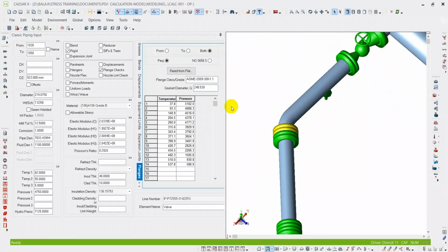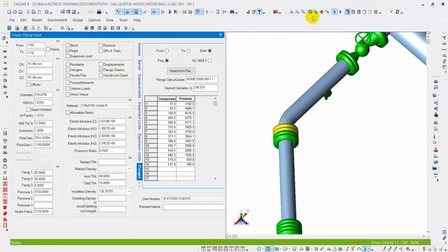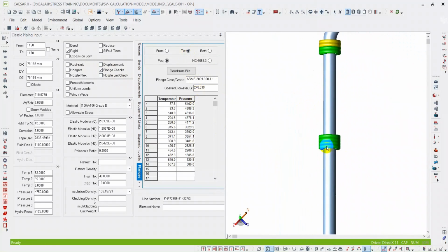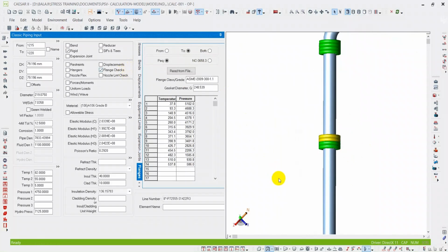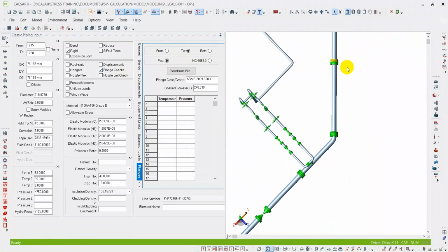Then go to this node and select flange leakage. So here we need to check the flange leakage at the center. So you have to define 2 because our modeling is like this. So we have the model like this from here and it is continuing. Okay. So you have to select 2 here and here also. The same has to be repeated. Flange 2. Okay, now let's see up to here. You have to model properly.